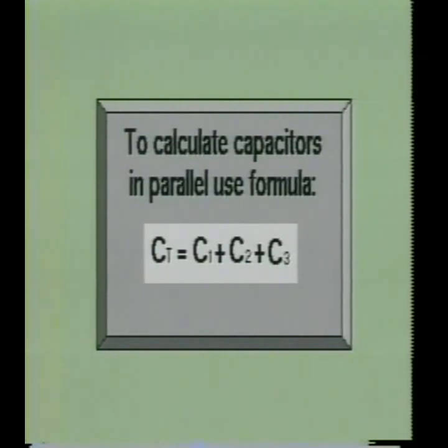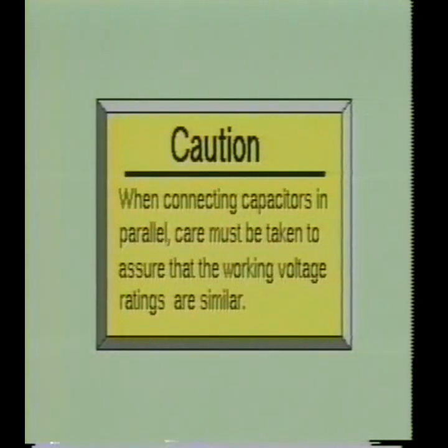When connecting capacitors in parallel, care must be given to assure that their working voltage ratings are similar. The reason for this is the highest voltage the parallel combination will stand will be determined by the capacitor with the lowest voltage rating.